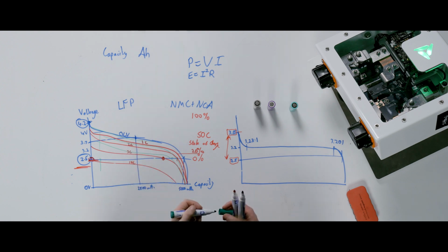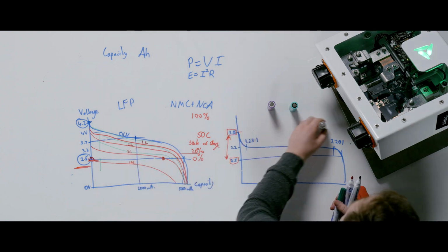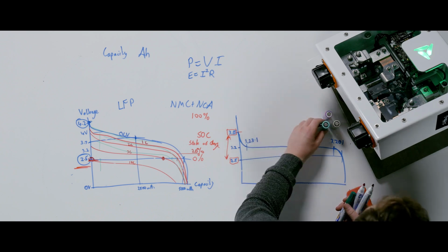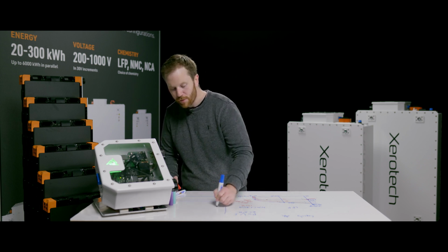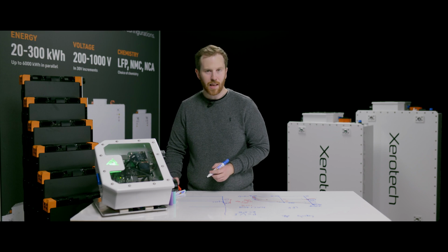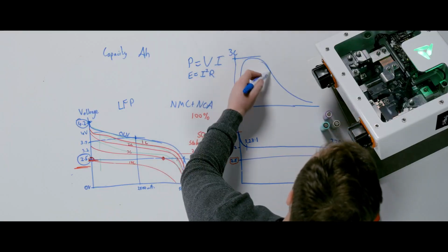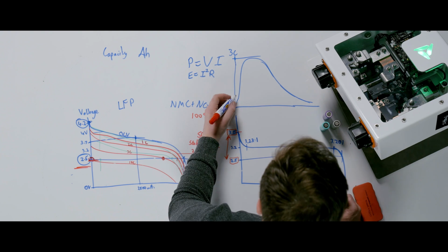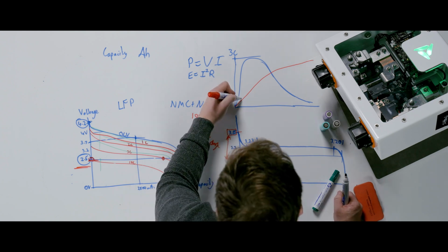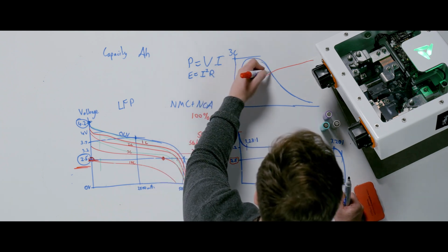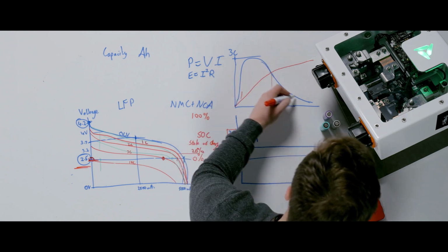the current. So that's actually very interesting. If you look at a modern electric car, when we say something can charge in 20 minutes, or you want to do a 2C fast charge, it's not actually doing a 2C fast charge. For example, a Tesla at a Supercharger might have a charge curve that starts off low, gets very high, and then tapers off, down like this. And this peak here might be up around 3C, but then rapidly tapers off because the voltage and the state of charge of the battery is increasing rapidly as it goes up here. So as it's nearly empty, it can take huge amounts of power in this region here. But when it's nearly full, it can take less and less power.